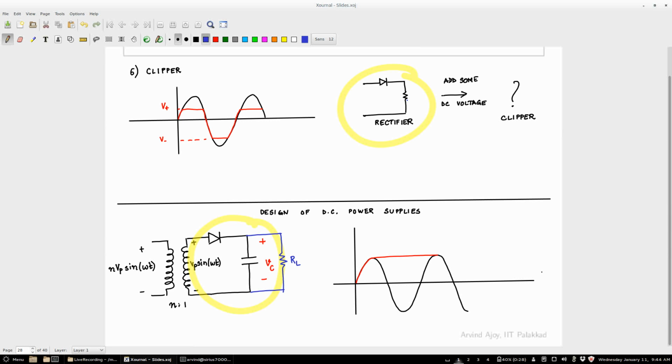So if you go back to your rectifier, the half wave rectifier which had a diode and a resistor, to filter it you would have to put a capacitor. Another way of looking at the circuit is to start with a peak detector and then connect a resistive load to it. Both are just two ways of looking at the same circuit. Now once I have this, it's going to discharge. How will it discharge? How will the discharge appear? In which region will it discharge?